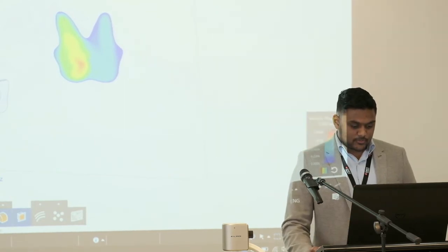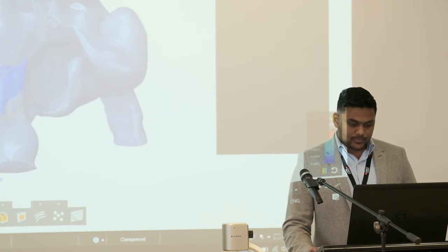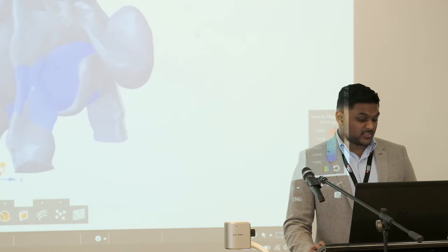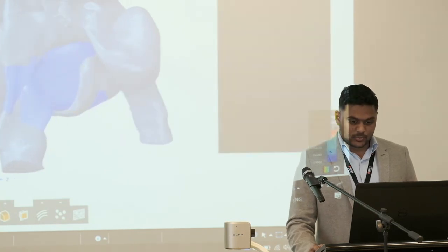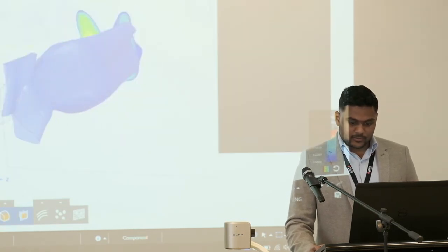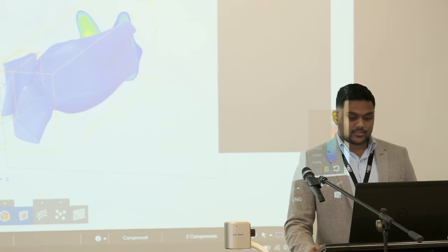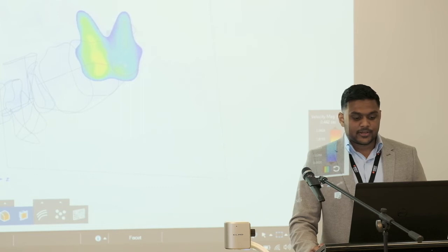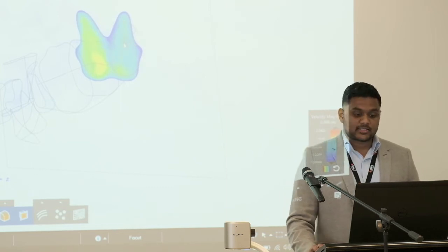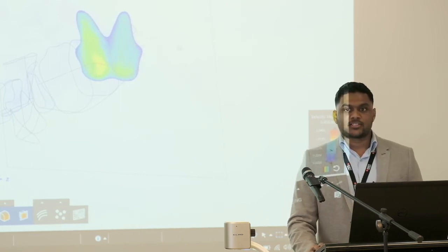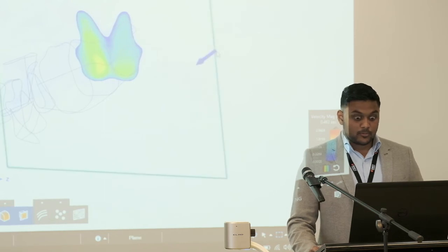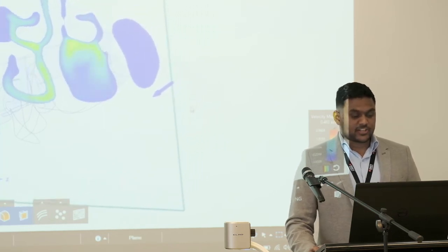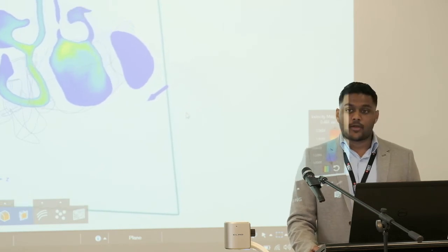Now I've got these two components that I'm going to add to the flow, right? So I'm opening up the section towards the front, and maybe the doctors can do something that opens up that whole section as well. Again, if we have a look at these things, right-click, we're going to add them to the simulation body, and we can see as I'm adding them to the simulation body, the flow on the right-hand side is updating, and now we've got flow that's a little bit more uniform. So again, I can take a section through, and I can see that I've actually added this volume to the flow around this region.